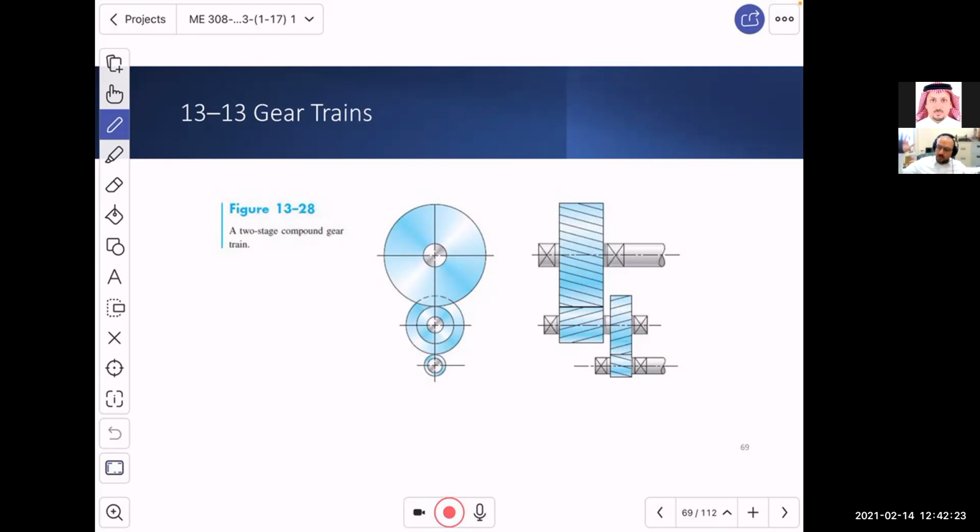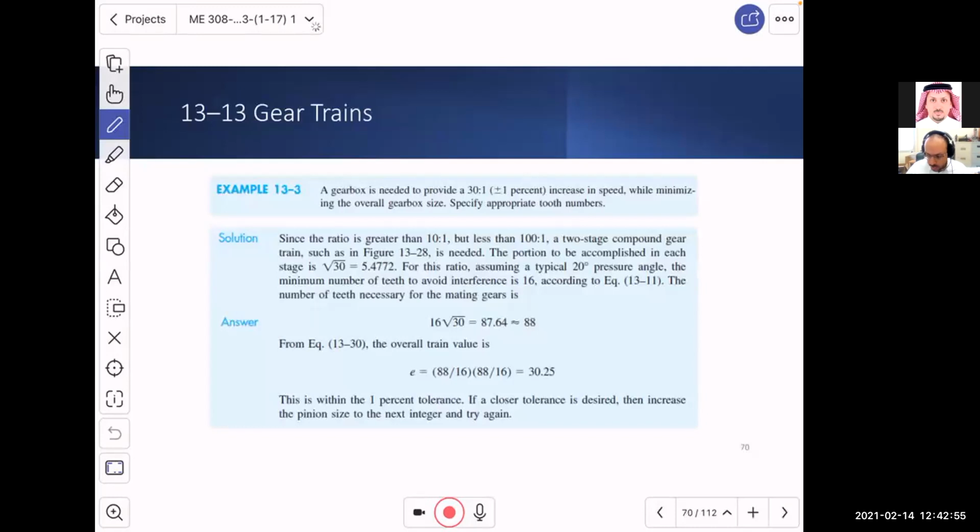When you want that turbine to supply the power to the pump, and the rotation is not matching, then you put a gearbox which is designed to reduce this RPM to that RPM, or increase this RPM to that RPM. So 2 stages will do. That's it, 1 stage and another. So 2-stage gearboxes are very common.